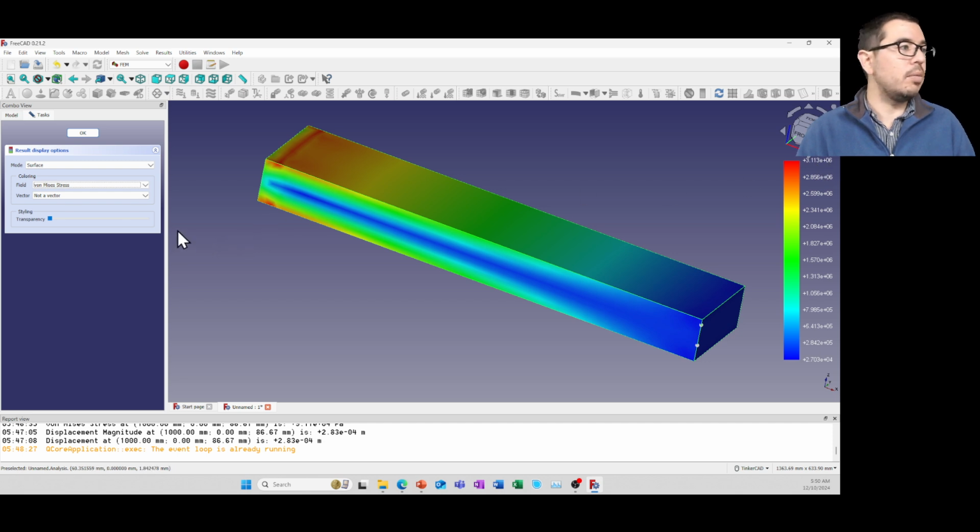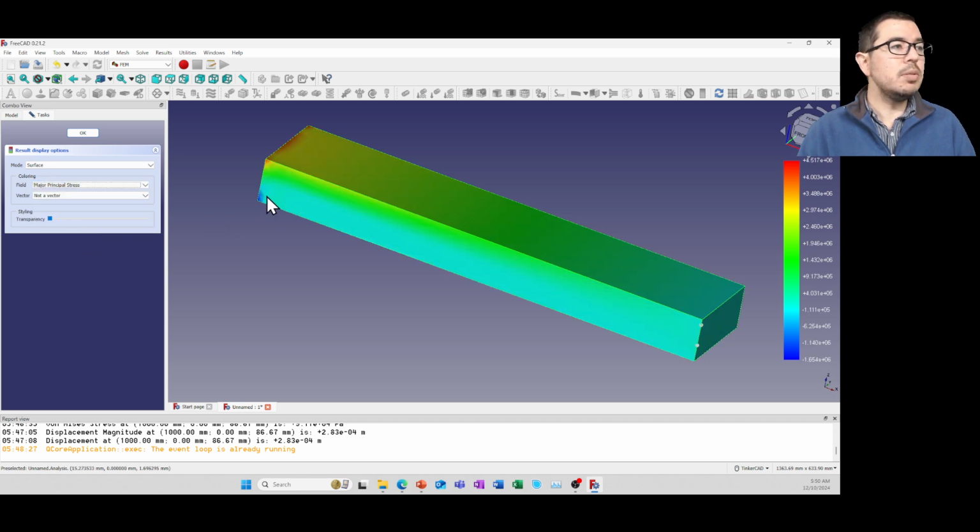With the von Mises stress, we can also, instead, if we want to use, say, a major principal stress, so this is going to be the sigma 1 value, we can see that these values get a little bit higher. They're at 4.5 megapascals. Remember, there are Poisson effects happening here as well, so that can lead to some issues.